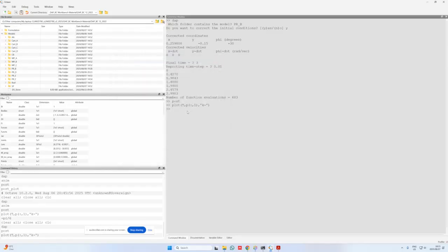Okay, so a few other things that you might want to plot is, let's say, the X and Y coordinates against each other for this system as well. To do that, I can say plot, then I'm going to plot the X coordinates. I'm going to start off with R. It's a 301 by 1 by 2 matrix that I have. So I'm going to plot it for all time steps for body 1, and I'm interested in the X coordinates. So my last entry over here will be a 1.